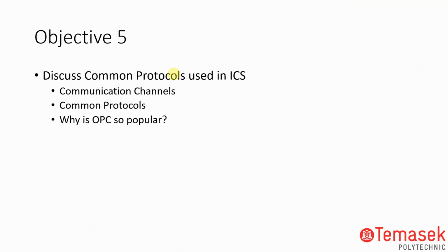Basically, it can be your RS-232 or your, what do I call it, the RS-485. Basically here, either it sits under Ethernet or Modbus, or IP, or the Profinet, which is Siemens, and the other one is the EtherCAT. Okay, most industry are using this. Of course, there's a whole lump of them lah. Later we'll go, I can go through some of them lah. But then, these are at the baseline. The lowest level is basically Ethernet.